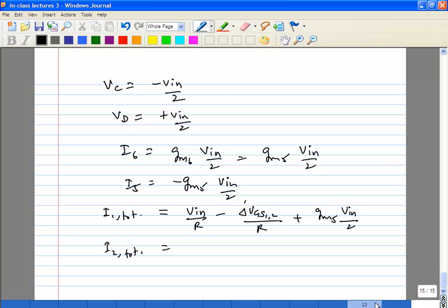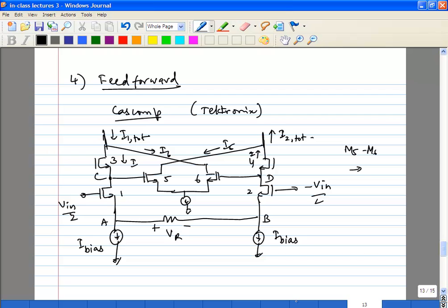Because the gain of these two guys, input to C, the gain from input to C is approximately -1, because the input impedance is approximately 1 over gm of this guy. I'm assuming, in fact, all sizes are matched right now. Almost. Well, these two sizes, 1, 2, 3, 4 are all matched. And 5 and 6, you're going to size them based on how you want your error. So that's what I'm getting to here.